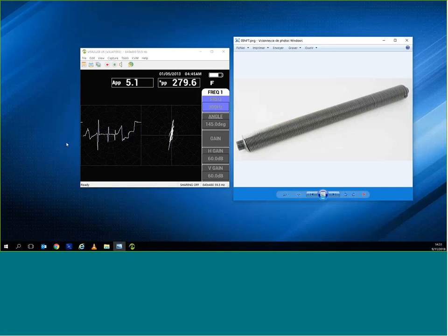The reason they're not as clear is because when you're using a differential probe, you're comparing 2 coils side by side. So as you're going through a taper, at the beginning you might have a very big difference, or at the end you might have a big difference, but all the way through the difference is very small. The difference is much smaller. So this is what we see. So using NFT differential, we really get a very clear pitting signal.